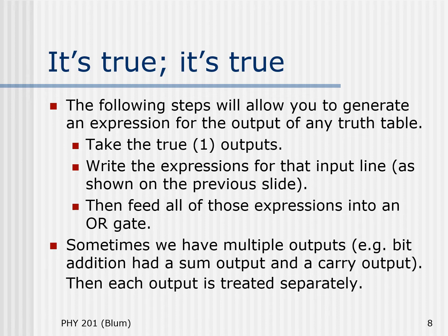So here's our approach. Take the 1 outputs. Just completely ignore the 0 outputs. Take the 1 outputs. Write an expression for those 1 outputs. So write the expression for that row if that row has an output of 1. And then when you have all those expressions, we will OR them, and then that will be a full expression for the full table.